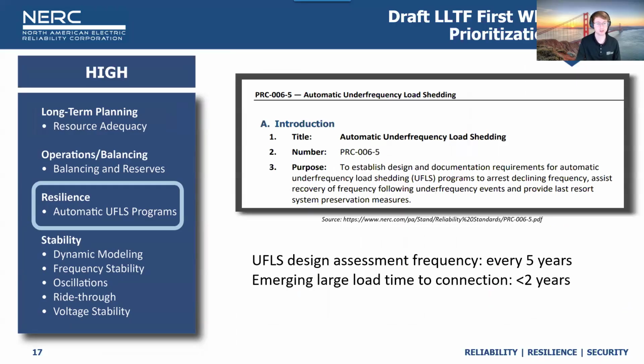Additionally, we see some issues with the existing UFLS programs. You would do the assessment about every 5 years, at least as required by the standard PRC-006-5. And of course, we've already covered that certain large loads can connect in under 2 years.